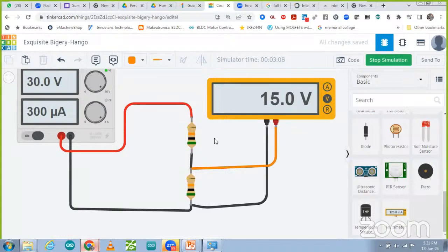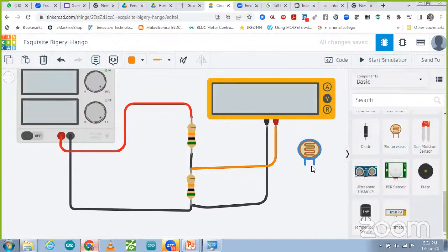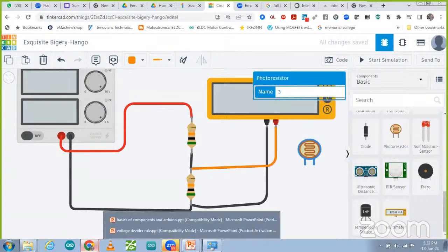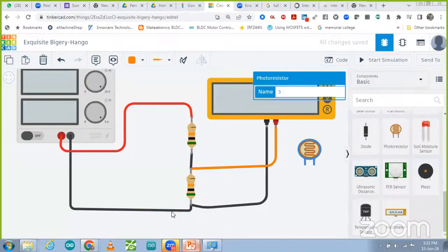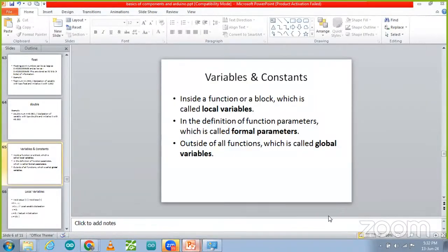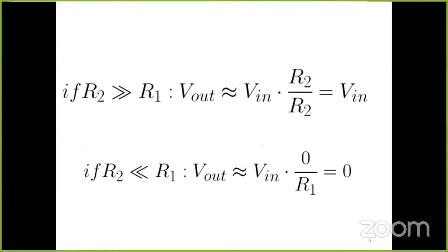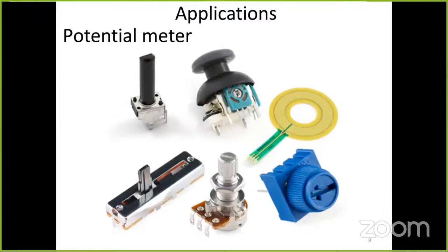So this one is the voltage divider rule. Where are we going to use this voltage divider rule? Whenever we are going to use any kind of resistive sensor, over there we are going to use the voltage divider rule. Let me elaborate over here. Whenever we use any resistive sensor like these, you can see a potentiometer we are using, a slider, and this sensor is a force sensor, and we are using an LDR sensor. These sensors work based on the voltage divider rule.